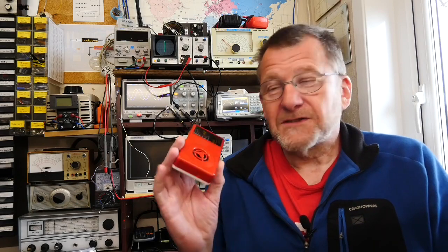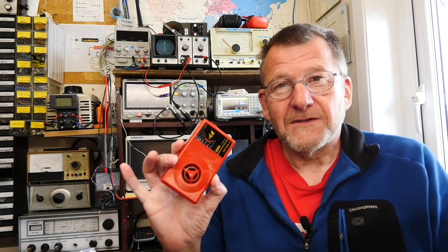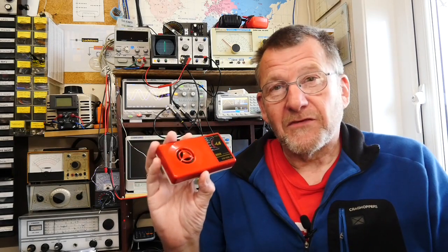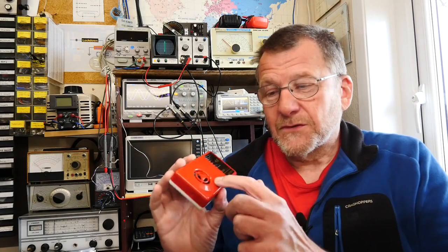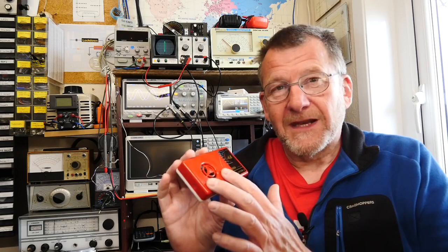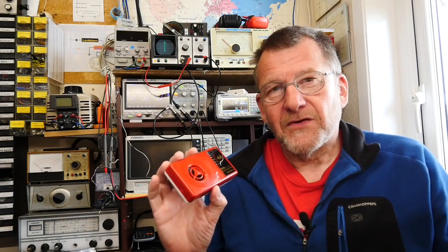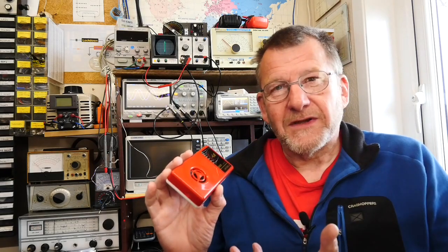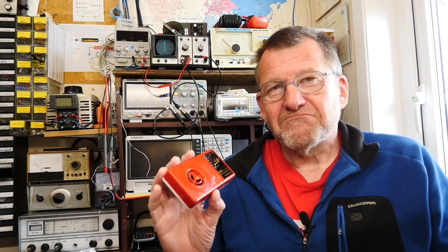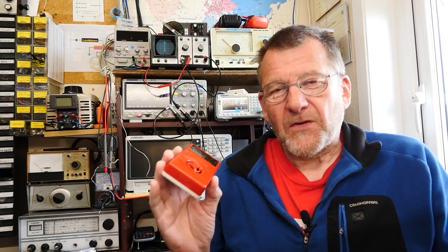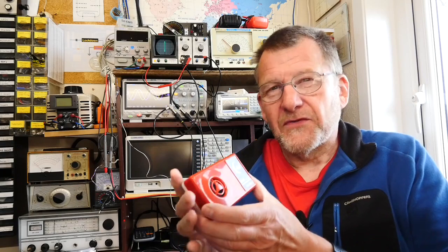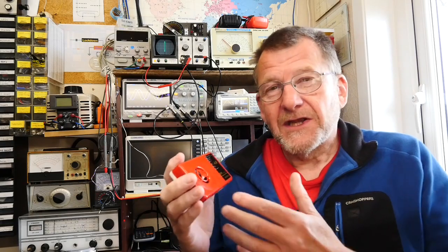For example, this HX108 little Chinese radio kit that some of you may have watched me build in some previous videos, if I were to swap over the wires that are feeding the loudspeaker, I would effectively be changing the phase by 180 degrees. Would the radio sound any different? Well, no, certainly wouldn't be able to tell. And certainly for a lot of mono things, that probably is the case.